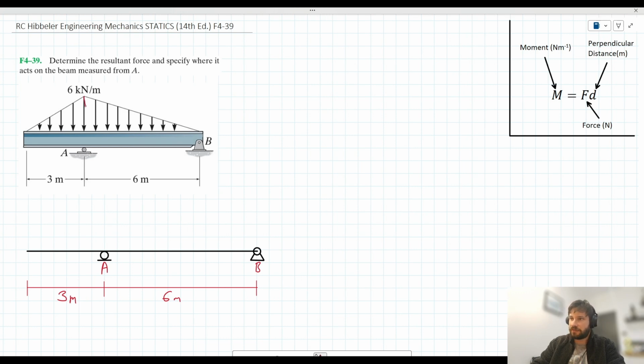We could say we have one distributed load here, which takes this right angle triangle shape, and we have another distributed load here, which also takes a right angle triangle shape. Let's first concern ourselves with the position of these point loads, if we're to convert both of these distributed loads into point loads. If you didn't know already, the point load conversion of one of these distributed loads will act down from the centroid of the shape.